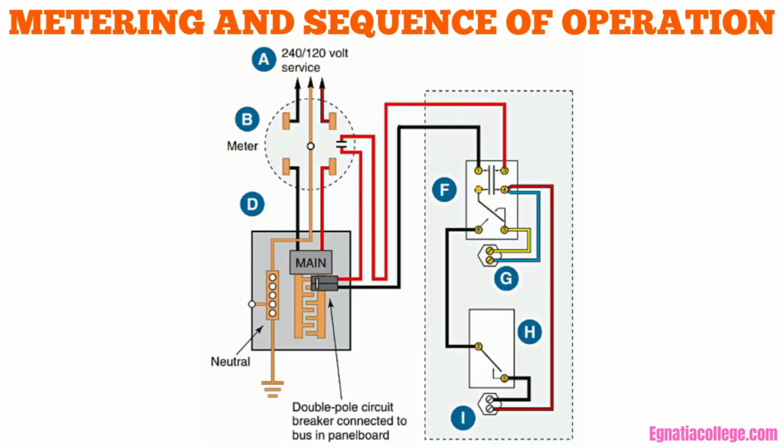3. Connect the water heater circuit, as shown in this figure, but install a time clock in the circuit leading to the water heater. The time clock would be set to be off during certain times of the day deemed peak hours by the utility. The utility gives special incentives to the homeowner for agreeing to this arrangement. This is a good conservation method that many supply authorities are promoting.